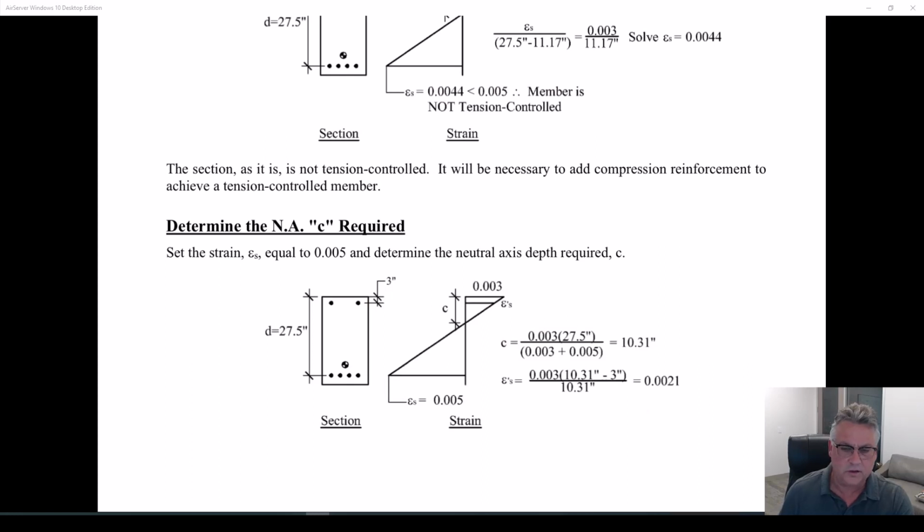You may be asking yourself, why am I using that 0.00207? I like having the 07 in there because that's actually the calculation to decide if you have yielding, fy over E. The debate and the discussion we had before was, what number do we use here? And for that number, epsilon y in tension was taken as 0.002. I'm just an old guy.